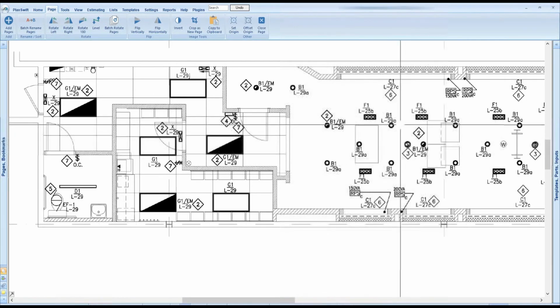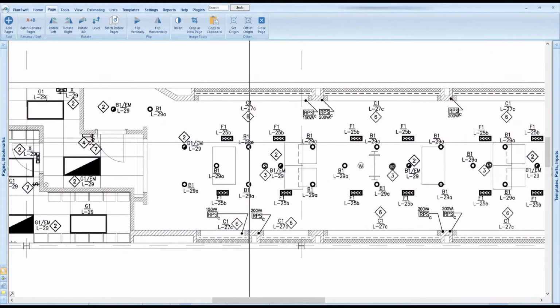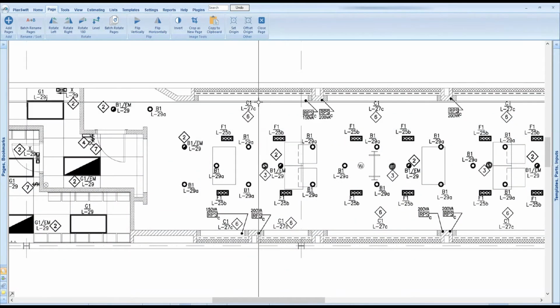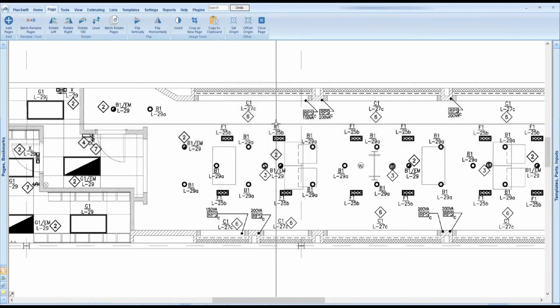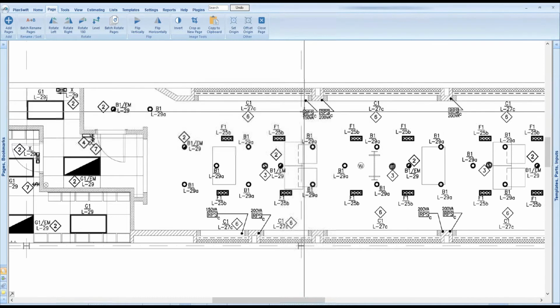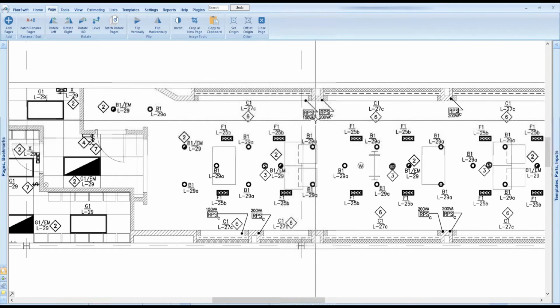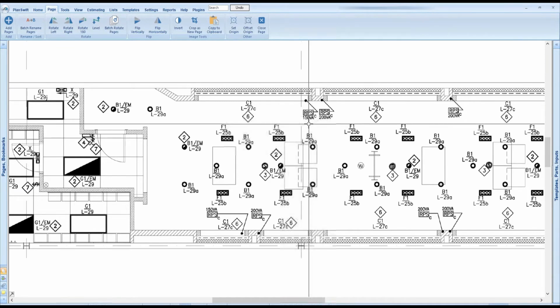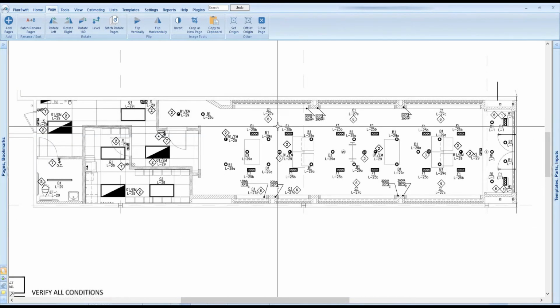Now here's what I want to point out. I happen to know, because I looked at the notes, that C1 light fixture is actually a linear tape fixture. And I also know that these RPSs are actually low voltage power supplies and they have different VA ratings, okay? So I'm going to count those also. Now, let me show you how I do this. Again, the purpose is just count them lightning fast, but accurate, so I can send off for a price for fixtures.